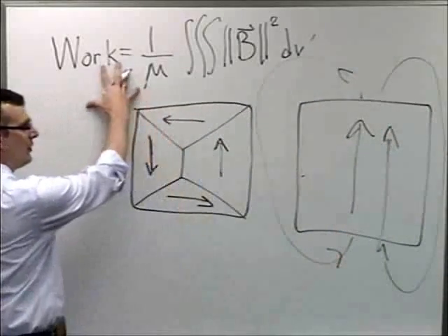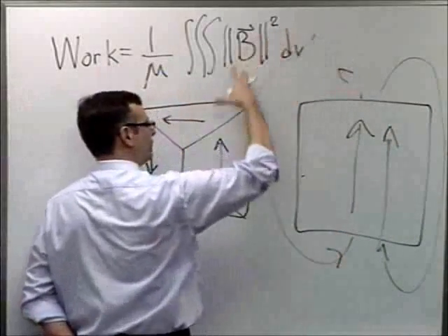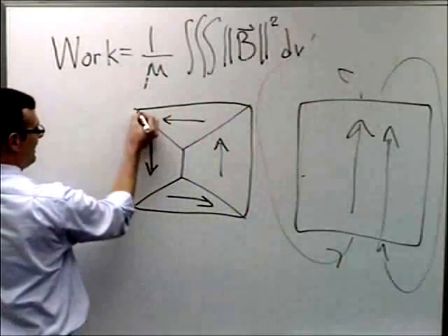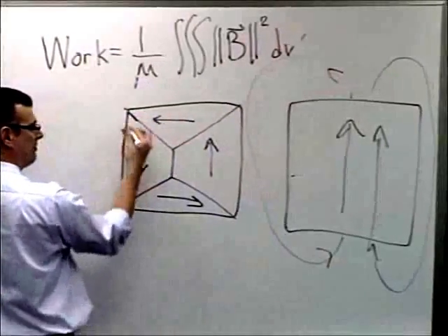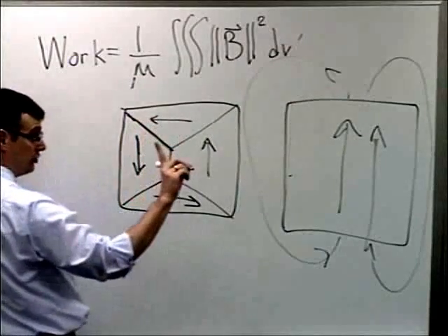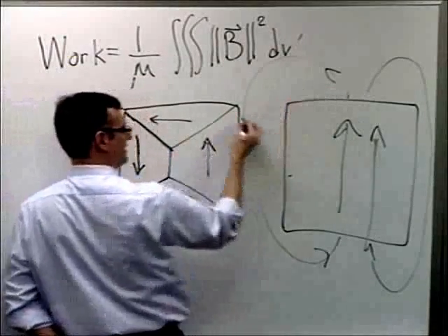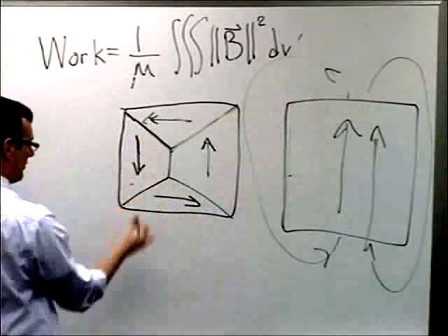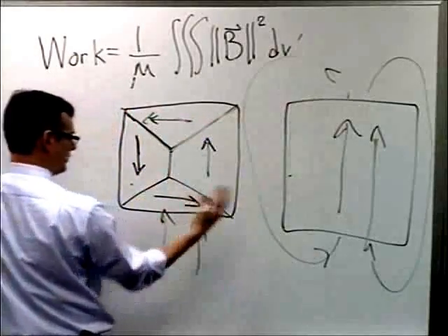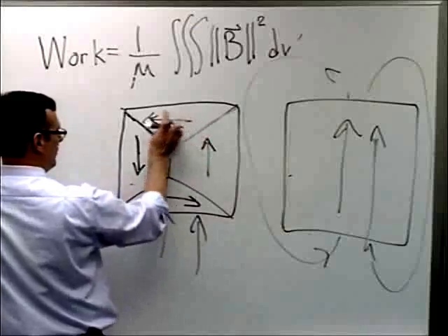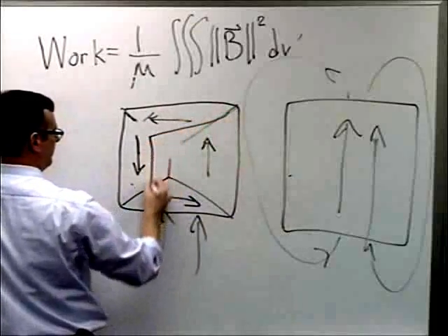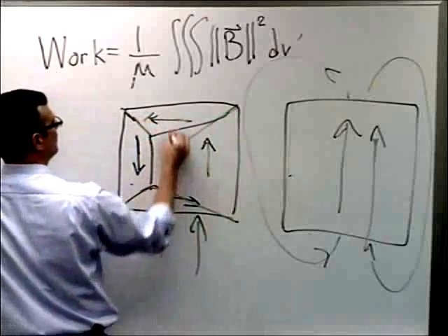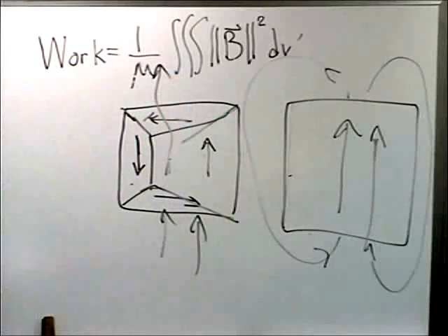If you look at this equation, having a whole bunch of flux outside the magnet takes a lot of energy. So you will actually make a domain wall. The material will set up domain walls, which take energy, but not nearly as much energy as this. And in doing so, you will circulate the flux inside the material. If you impress an external magnetic field, you'll get a strong response, and these domain walls will actually move to conduct flux through them.